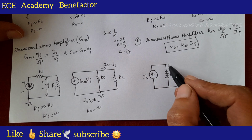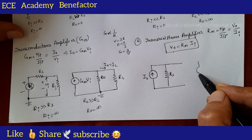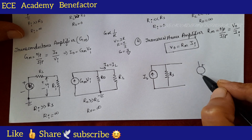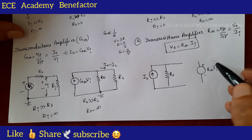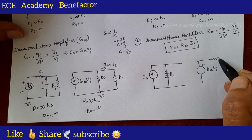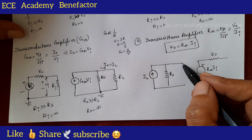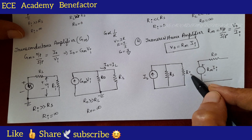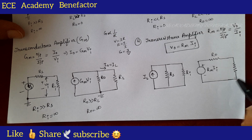This is the input circuit. At the output circuit we need to place a voltage source. What should be that voltage source value now? That should be Rm Ii. As there is a voltage source, there will be a series resistor R0. This is the output circuit. At the input circuit we need to place a resistor Ri. At the output side we need to place the load resistor RL.